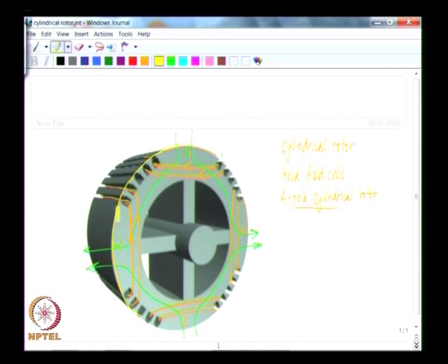For generating the rotor field here, you have a field winding in these 2 slots connected in series with the winding here, and then the third pole face and then the fourth field winding. They may all be connected in series to ensure that the same current flows through them,